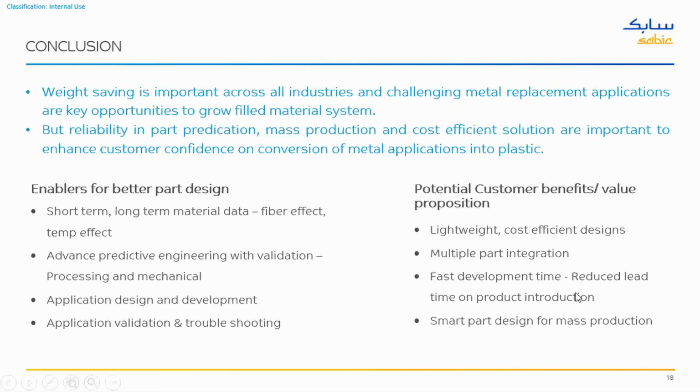And surely we can also look at smart part designs for mass production. Here, smarter design with the filled material uses the Moldflow software to its optimum, where we can design the gating sequences to see how we can optimally orient the fibers within the part, considering how the load path goes within that part, and that way we can use the fibers to their most optimum. So that's very important, where we can connect the process design and the material aspects of it. So with that I would conclude my presentation.